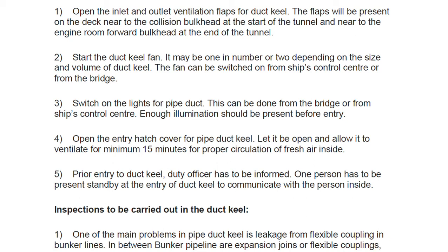Prior to entry to the duct keel, the duty officer has to be informed. One person has to be present on standby at the entry of the duct keel to communicate with the person inside. So one person has to be standby. All these procedures are similar to what we discussed in enclosed space entry.